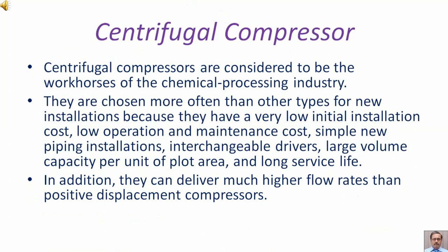Centrifugal compressors are considered to be the workhorses of the chemical processing industry. They are chosen more often than other types for new installations because they have a very low initial installation cost, low operation and maintenance cost, simple new piping installations, interchangeable drivers, large volume capacity per unit of plot area, and long service life.